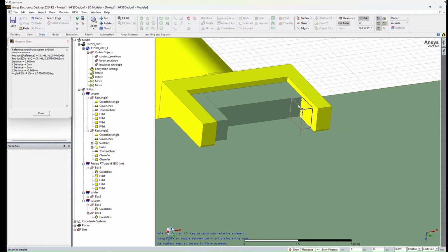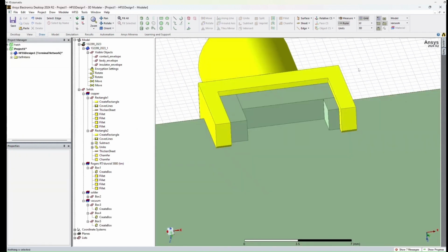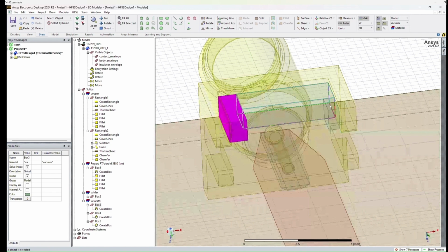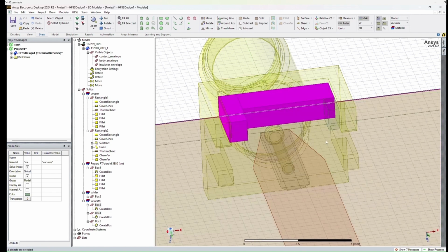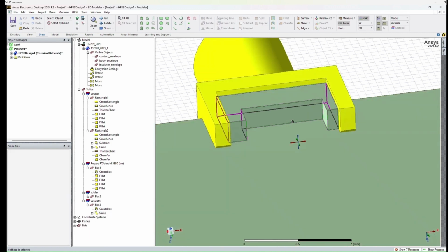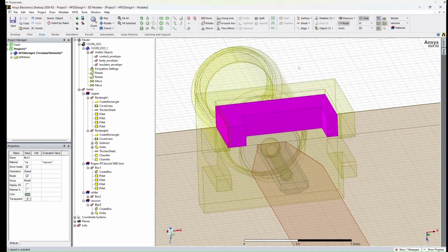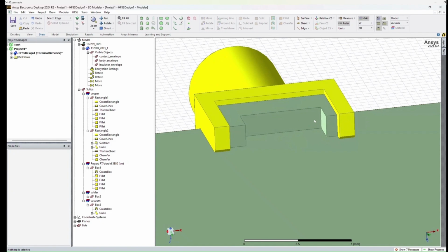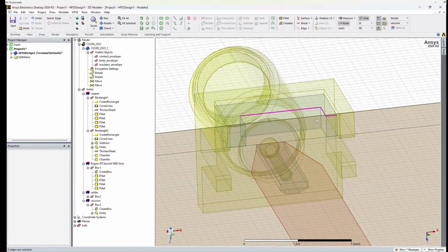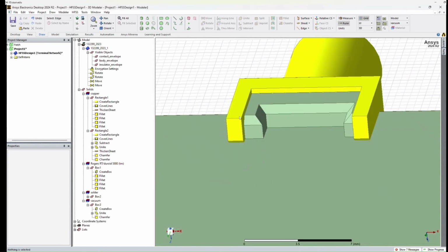And then once I've got these three boxes drawn, I can unite them to one object. I'll hit O on the keyboard for unite, and then not select the ground. Make sure I select the box, and then unite them. So now that's one object, and I can take it, select it properly and assign it a material. I'm first going to take these edges that are along the exposed edge right here and give them a 0.5 millimeter chamfer. That's something a little more understandable.